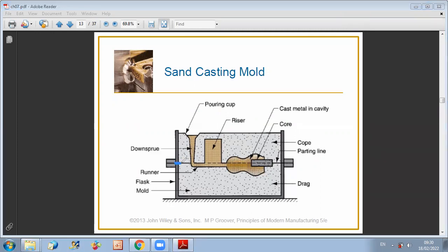So you can use something to hold it. Let's say you are putting a small slot like this. This will be rigid. It can be made of sand with adhesive or any other metal, that of course has a melting temperature larger than the melting temperature of your metal, because it should remain in the solid state.